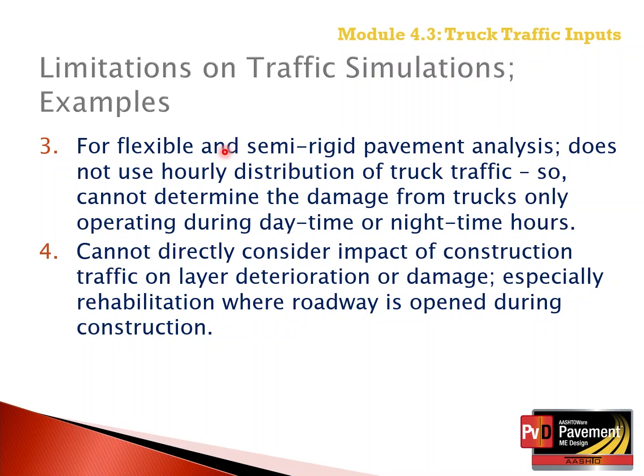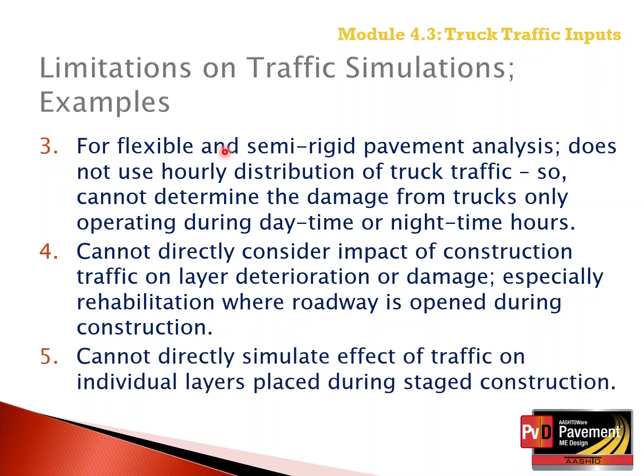relatively damaging to the existing pavement, even though it doesn't have many load applications. So, in other words, or in summary, we cannot consider stage construction or construction traffic for layer deterioration or damage. And it has to be considered independently. So it cannot directly simulate effective traffic on individual layers placed during stage construction.